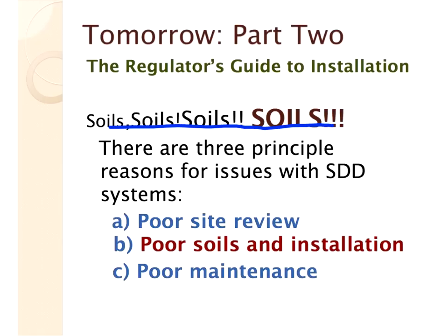But you get people doing this, and sometimes it's very annoying, but again, your regulators, and this is what you live with. Incidentally, we managed to fix that quite easily by ploughing in between the lines. There was 2 feet between lines, and we ripped up in between the lines, so as the water flowed down the slope, it flowed down into the ripped up area and percolated through into the soil below. But the contractor should be shot, or whatever penalties you have in Washington for that sort of thing.